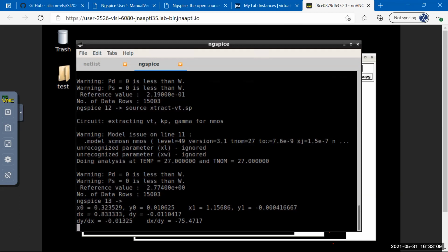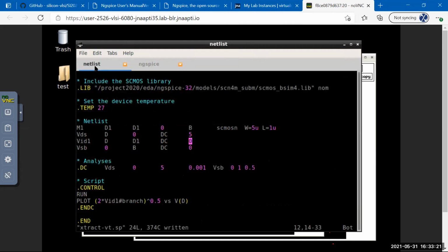Sir, I have sent the photo. Yeah. Excuse me, sir. Yeah, Priyanka. Sir, I have done the netlist code, but I don't understand how to run it in the NGSPICE. So you have finished the netlist. You've saved it, right? Shift W. Yes, sir, saved it. Okay. Escape from WQ. You don't have to do the WQ because we are using two different tabs.